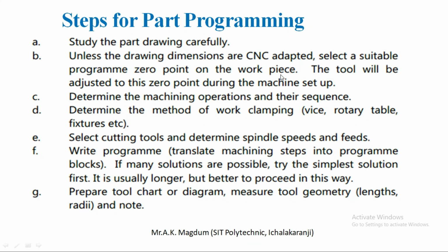Next one is the steps for part programming. What are the steps? The first step is very important: study the part drawing carefully. Before you start preparing the program, carefully understand what the part drawing is, what operations are required, and what dimensions are mentioned on that drawing. That should be clearly understood at the initial stage, then you move to the next step. Otherwise, if you don't understand the part drawing, it is very difficult to prepare the part program.